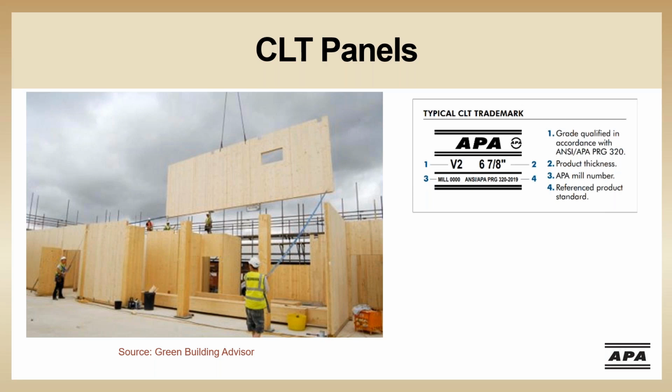So looking at some of the CLT basics and benefits, CLT is lightweight yet very strong. It's going to have superior acoustic, fire, seismic, and thermal performance. CLT is also fast and easy to install, and it should generate almost no waste on site. CLT offers design flexibility and low environmental impacts. And for these reasons, cross-laminated timber is proving to be a highly advantageous alternative to conventional materials like concrete, masonry, or steel, especially in multifamily and commercial construction. There's also the aesthetic and biophilia effect of exposed CLT panels in mass timber structures.